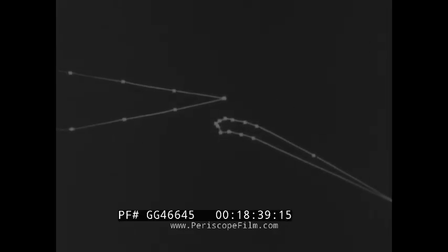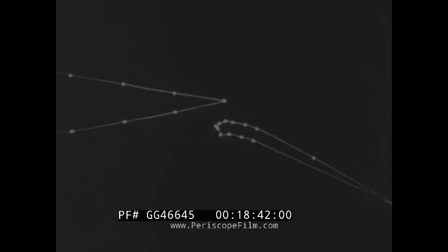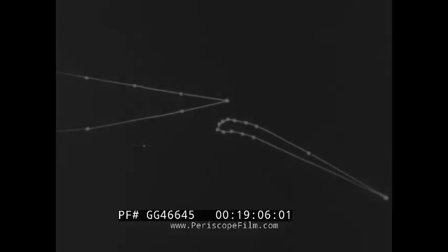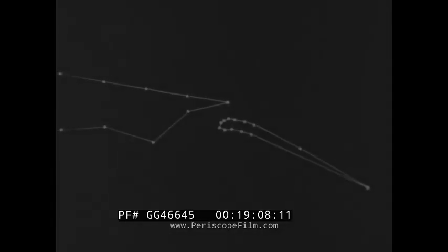Let us do it again. We move the tracking cross to the point where contour change is desired. Designate the contour point to be moved and command the move. Well, let us do it on a larger scale so we can really see what is going on. Notice that the contour point that is to be moved is blinking. I have just been accomplishing the operations normally performed by wind tunnel model designers and builders.